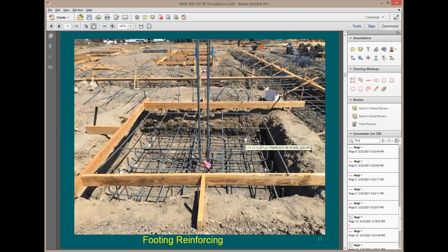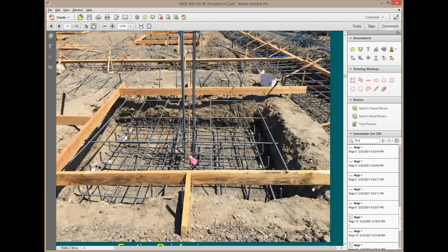Let me show a picture here of the actual construction. You see here, it does look pretty, right? You're going to see, wow, they just cut the soil and then pour the concrete. I'm going to say yes. Now, where is the form? Don't they do any form work around the footing? I'm going to say not really, because it's going to cost them money to put this form work. It is cheaper if they give you, for example, I'm asking you for 3-inch concrete cover, right? So they give me 6 inches. And I'm going to be okay with it. I mean, as long as you provide cover more than what I need, I'm going to be okay with that. So we should be fine.